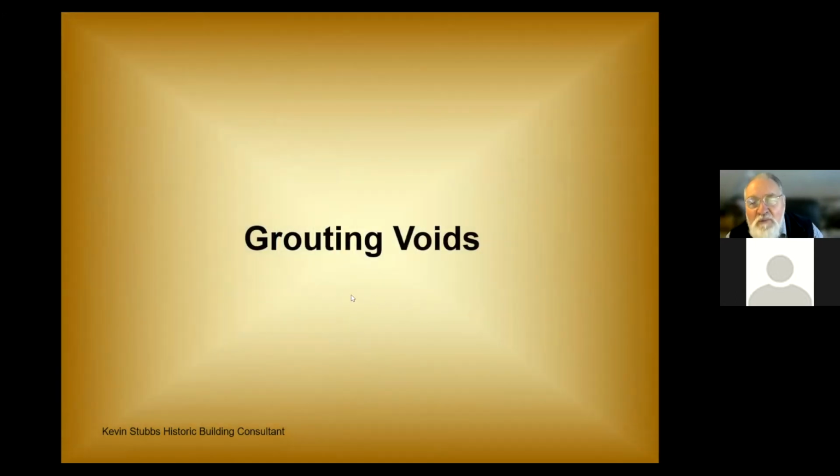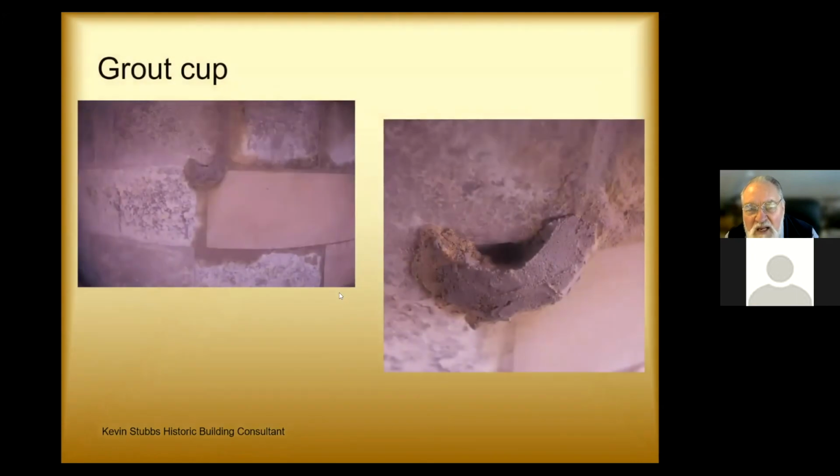Okay, well, the problem with many of our stone structures is that they have got a stone facing, a nice ashlar stone facing, but the core of them is rubble. And over the centuries, you've finished up with voids within that rubble core. And so you need to grout it. Or if you're replacing face stonework, you can never get all the voids behind fully filled with mortar.